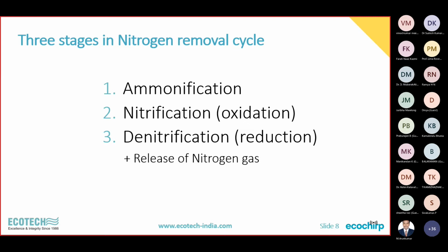Again, there are various differences. You have to be aware that the 25 to 30 milligram per liter total nitrogen we said earlier may apply in a typical residential complex. In residential complexes, there are a lot of other dilution waters, like from the washrooms, the bathing and the showers, which may not be the case in an IT park or a commercial complex where such dilution may not be available. And here the nitrogen content may go as high as 40, 50 ppm.